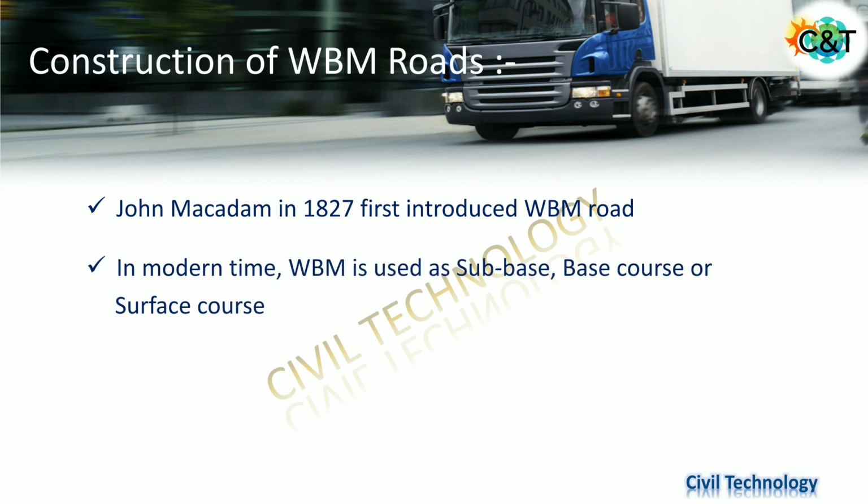So Macadam means preparation of a pavement base course constructed of broken aggregate that is interlocked mechanically by rolling action, and whatever voids are present are filled using screening and a binding material with the help of some water and some grouting chemicals. This is the definition of Macadam in current time. If you know the basics of the highway industry, you can easily understand this definition. But if you are not that aware, please clear your basics, and then you will easily understand it.